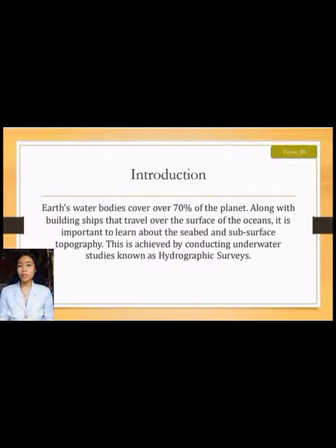That is why hydrographic surveying plays an important role in construction and planning of docks, harbors, and dams because it is important to ensure that the water depth in and around ports is sufficient to allow ships to safely enter and berth. And also surveying aids in flood control systems by predicting possible flooding zones and suggesting measures to effectively counter this. So the next slide will be the discussion of what hydrographic survey is all about.